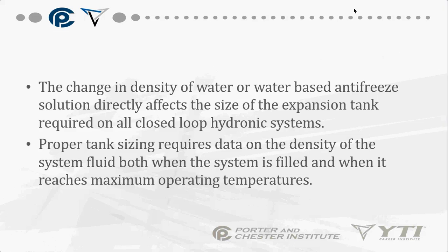But in a small system, Dave, we're talking about residential. Residential systems usually only have maybe 10 gallons of water really flowing through them. So it's not necessarily applicable to have an antifreeze glycol solution in that particular type of system.